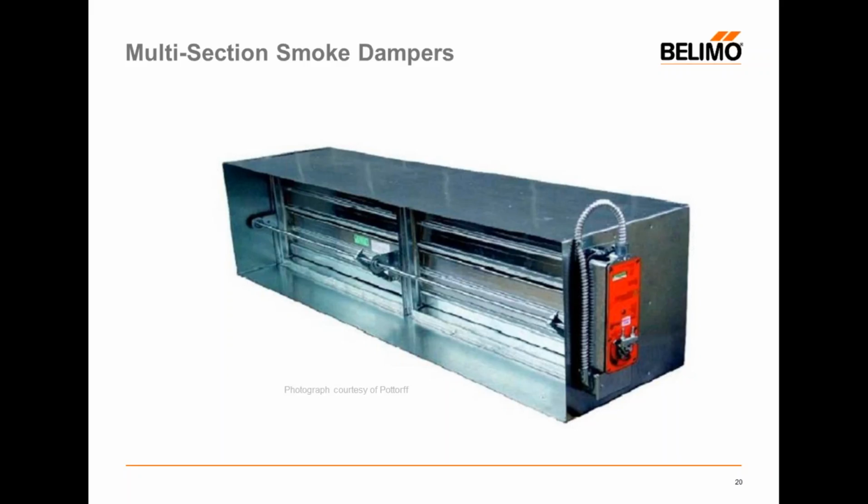You will find multi-section smoke dampers and combination fire smoke dampers. As long as our jack shafts and our linkages are true and the damper functions properly, this will work just fine for all applications requiring larger fire smoke or smoke dampers.